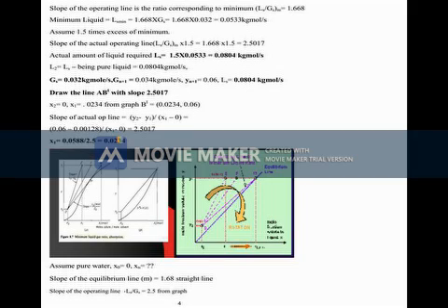Then entrainment, downcomer flooding, downcomer loss. Entrainment, you know what is entrainment? The amount of liquid that is carried away by the gas. There is an equation for that. Then downcomer flooding contains two parameters, downcomer loss and downcomer backup. You check all these things, and if all the parameters are met within the specified limits, then you can say the assumed tray spacing is okay.